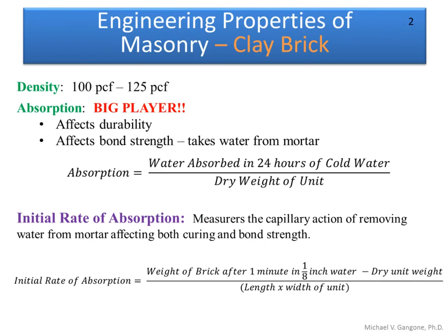So it is important to make sure that we maintain good water within the mortar mix so it actually fully hydrates and gains its full strength. So it's important to measure the initial rate of absorption of a masonry unit, and this is how you'd actually go about measuring that initial rate of absorption.